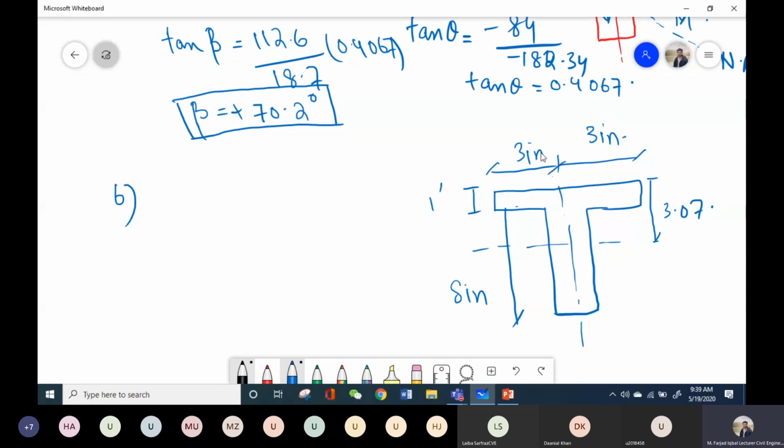Okay. So to find the maximum bending stresses, I have to use again this formula that we derived, Mz y over Iz plus My z over Iy. Now you can visually look at this picture and figure out where maximum bending stresses will occur, because for every case Mz and My, Iz and Iy will remain the same.